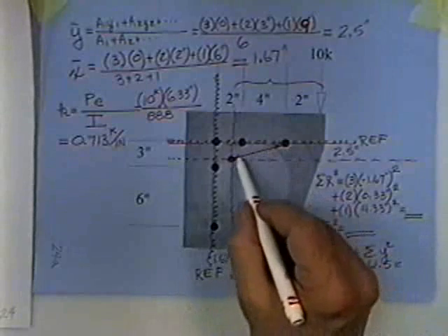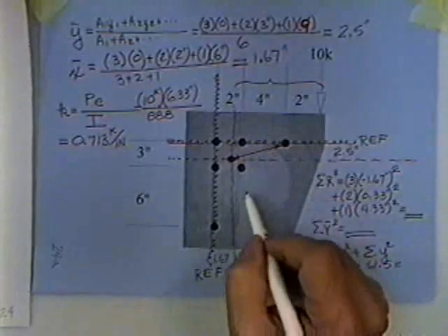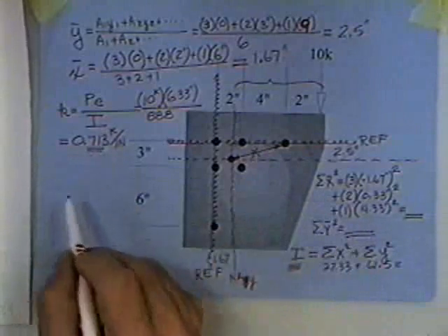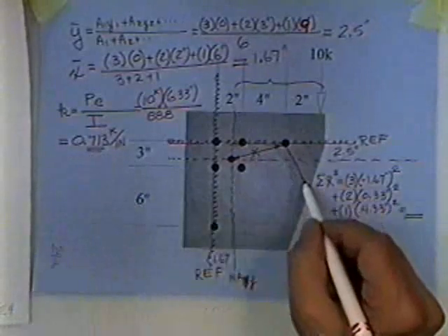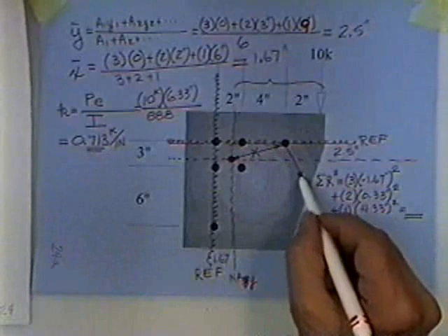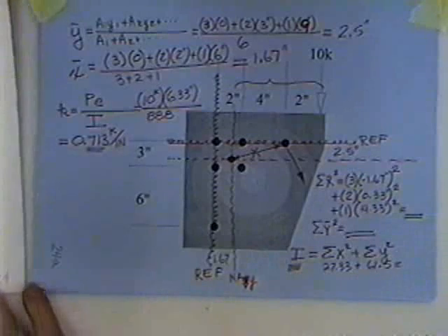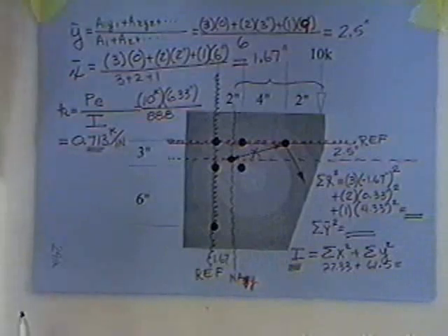You find that distance right there by trig, multiply that distance times 0.713 kips per inch, and that'll be the total force acting on that bolt. So you can design that bolt. An example is down on the bottom of page 24.